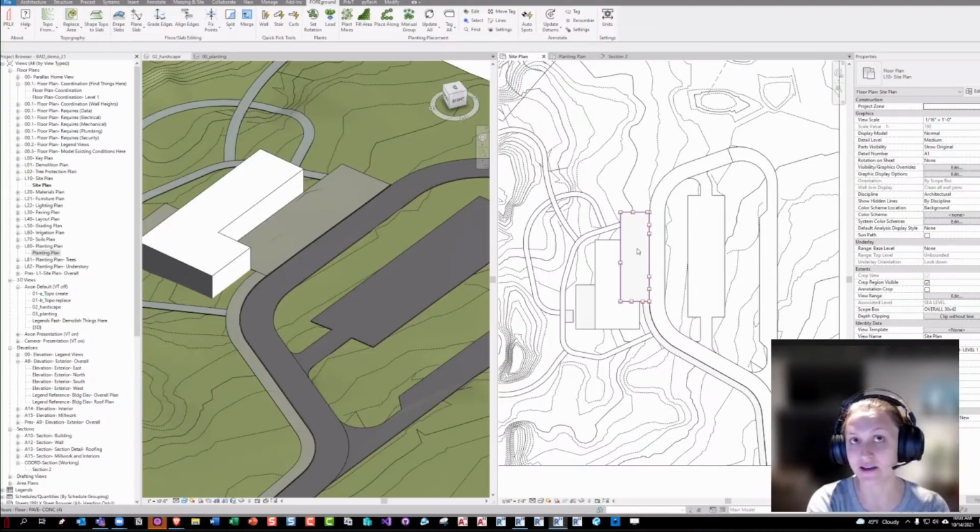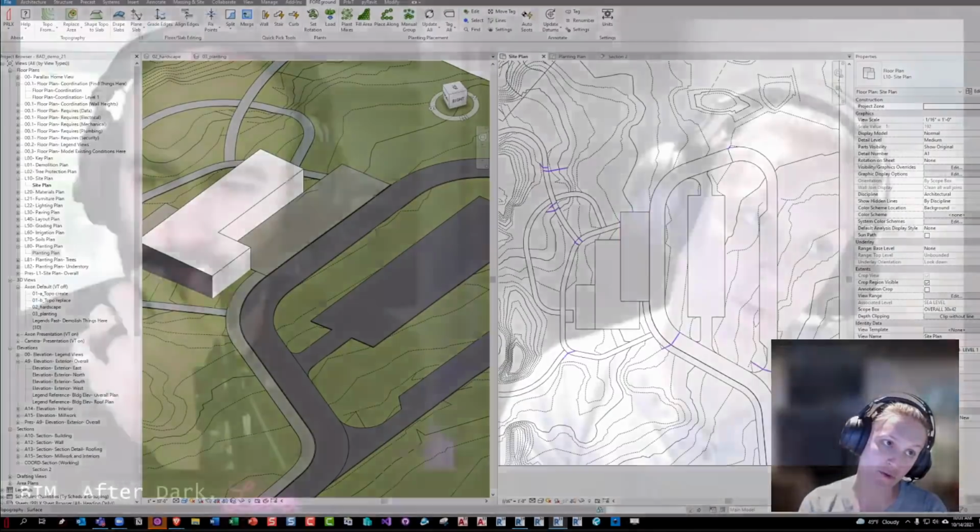The slab tools and drape will work with it. The nice thing about bringing in a civil topography via Link Topo Surface, if people know that workflow, is that it's a different kind of topography that maintains its shape from Civil 3D, so you can export it out and then link it in. But then you can't edit it. It's not made of points, it's made slightly differently, and it becomes a static object in Revit that can be updated, but you can't touch it.